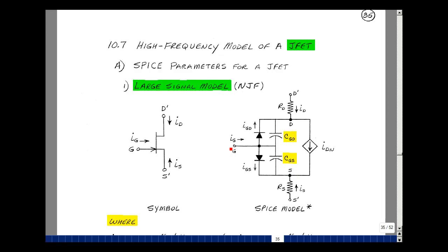And what's odd here is there's no resistor for the gate. Just labeled this as just a gate by itself. I believe the reason for not putting a resistor here is that these 2 diodes are reverse biased. There wouldn't be virtually any current coming in here.